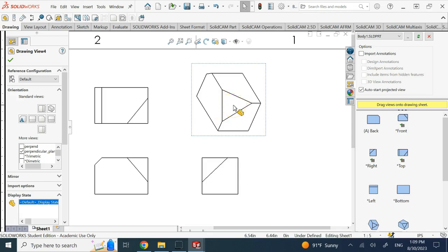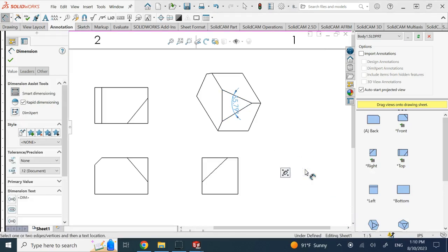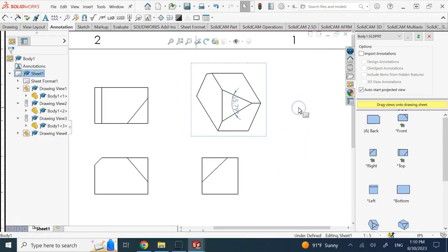And that's one way to show the true size, or if you want to see other things of this object. For example, if I wanted to know what's the angle between two of the edges, clearly I'm not going to find that angle in any of these views because these angles are not right. If I want to find the angle between these two edges, then I definitely need to see it full scale like this, and then go ahead and measure this angle, right? Like that. Okay, so it is very critical to show it full scale.